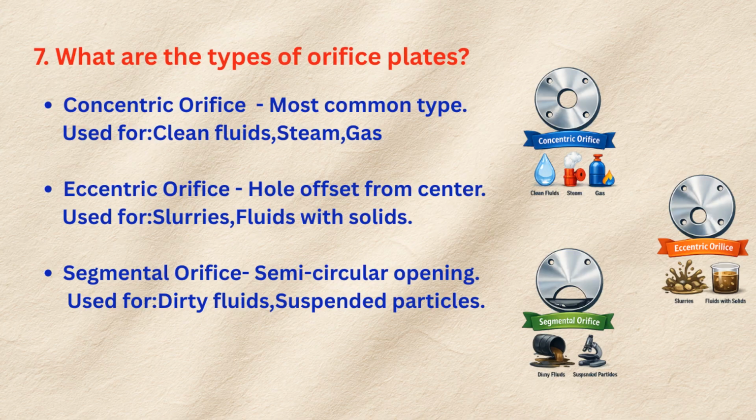What are the types of orifice plates? Concentric orifice, most common type. Used for clean fluids, steam, gas. Eccentric orifice, hole offset from center. Used for slurries, fluids with solids. Segmental orifice, semicircular opening. Used for dirty fluids, suspended particles.